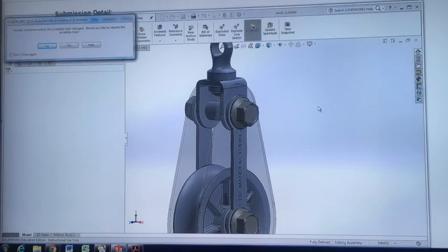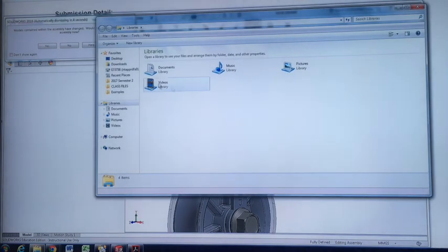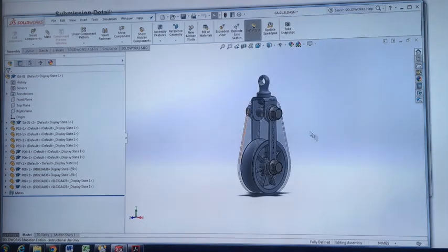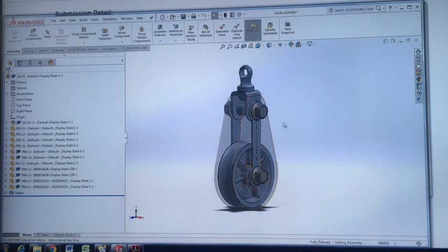All right, so rendering. The software I'm going to use is the SolidWorks rendering software, which is improving all the time. It's not necessarily the best rendering software out there. I now use KeyShot more and more. KeyShot has a plugin with SolidWorks. You basically install it, and there's a button you can press to export to KeyShot, and it will link the files. So when you update the model in SolidWorks, it can update in KeyShot as well.